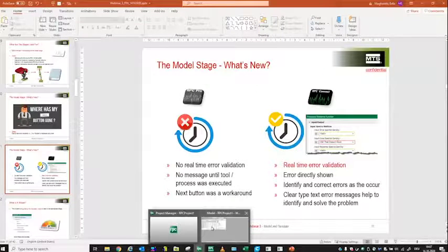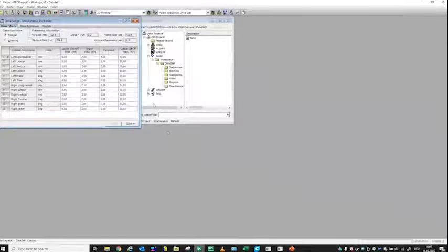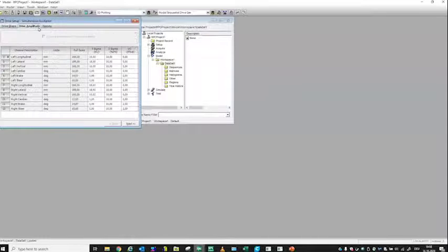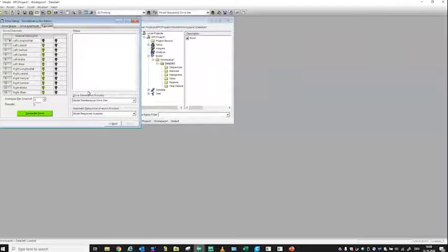Now I'm opening RPC Pro, and we are in the model stage defining our drive shape. Imagine we have a lower cutoff frequency here, and we want to define our drive shape. I do something silly, typing in a low cutoff frequency of 5. Everybody knows that the break frequency has to be higher than the lower cutoff frequency, of course. But RPC is fine with that. RPC Pro is not arguing about that. When I switch here to the drive amplitude and then go to the execute tabs, we don't see any problems here.